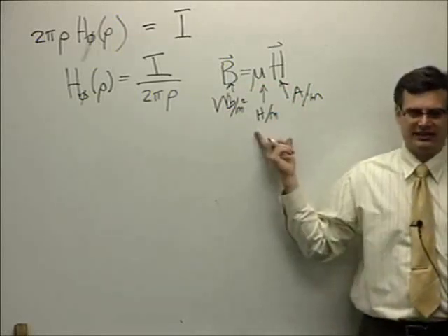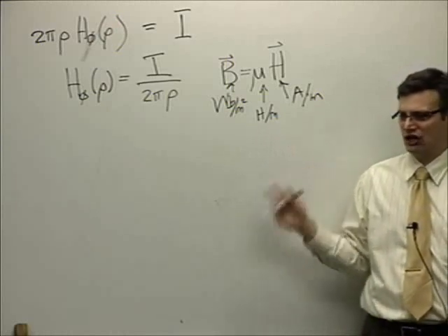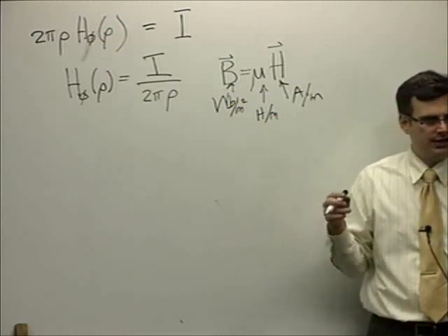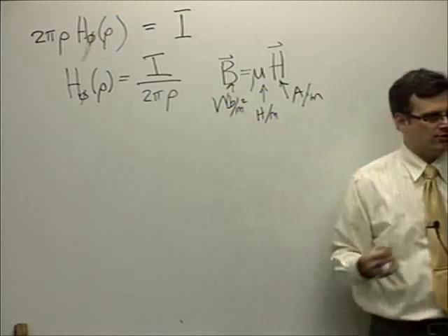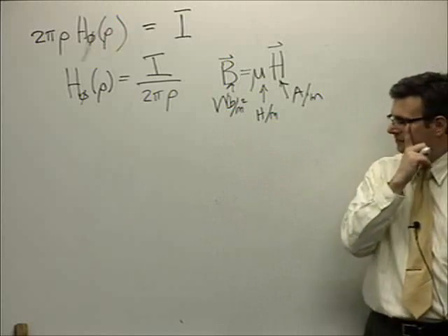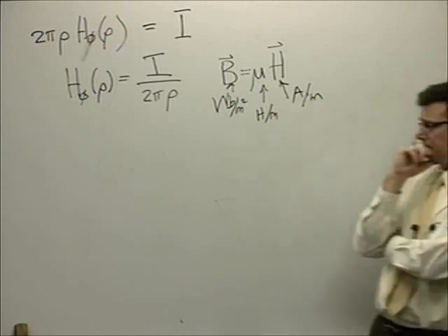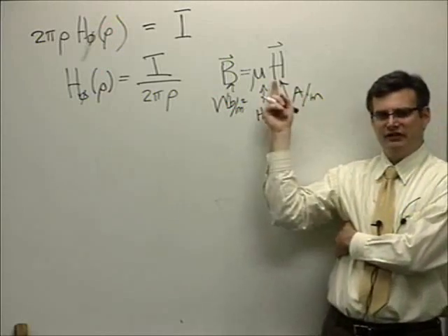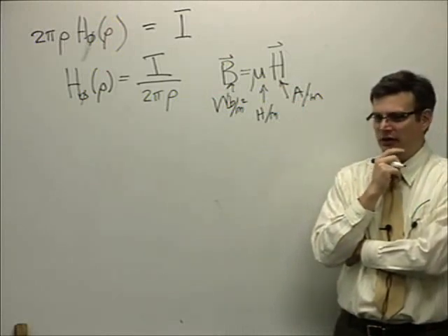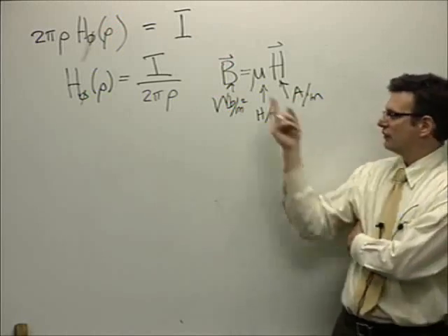These are the units I like to use. Units in magnetic fields and magnetic materials get crazy. We have Gausses, Teslas, Webers, Oersteds. Stick with Webers because they're more SI compliant. That's my recommendation to the class when people measure magnetic fields. And I will give a lecture maybe the last week of class about where mu comes from. Remember I explained in about 5 minutes where epsilon came from? It would take me about 5 months to explain all the different varieties of mu.